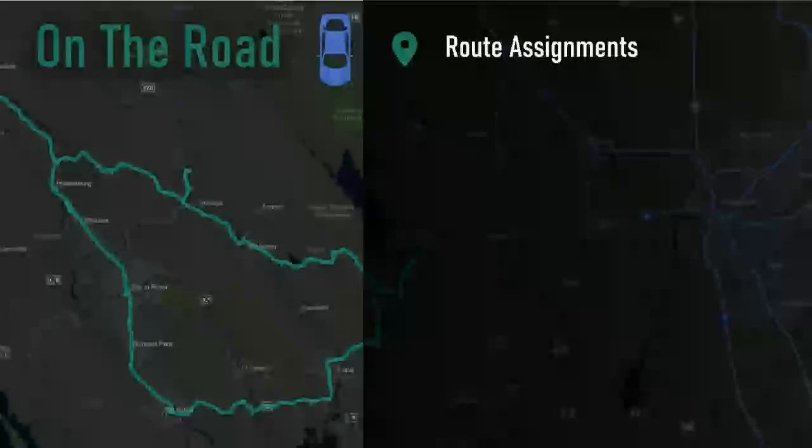I have another question from Carzon. Do you drive all the curves within the study roadways or apply any high-level screening? Typically, we have driven all the roadway networks. We don't screen particularly for curves. That's part of the efficiency of this and having the database. Something that might be considered a curve needing treatment for a certain posted speed right now, if that speed limit goes up, it may not require treatment right now, but if the posted speed limit is raised, it would require treatment.